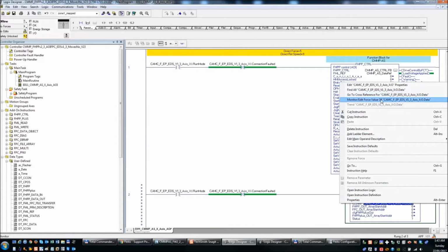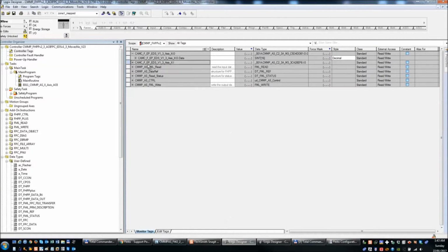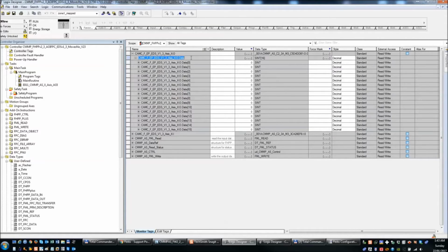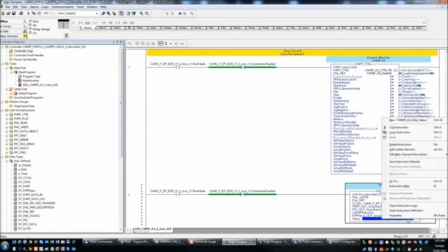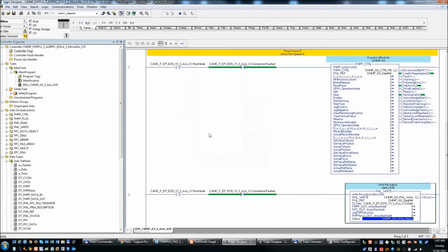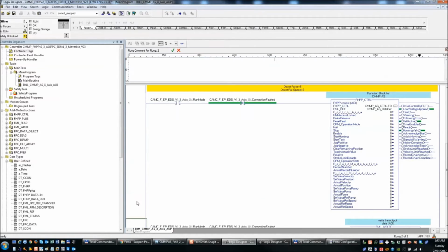Again, if you go to monitor, so now we're dealing with outputs. So this is the tag I just put there. We're going to be starting with this byte 0 and then byte 8 for the next 8 bytes. So again, FHPP out is byte 0, FPC out is byte 8. And we need a status for that. New status. And good.